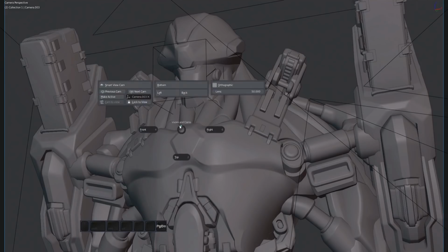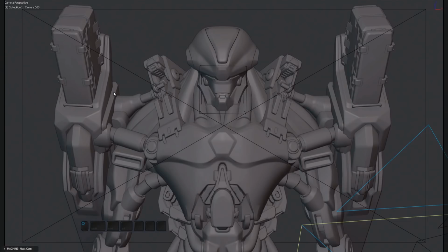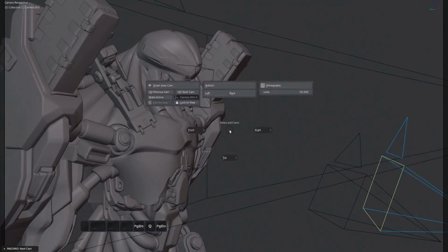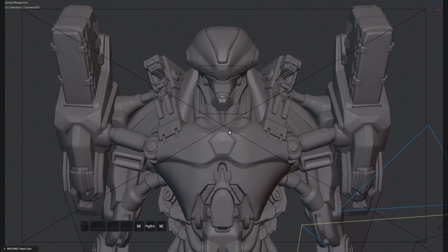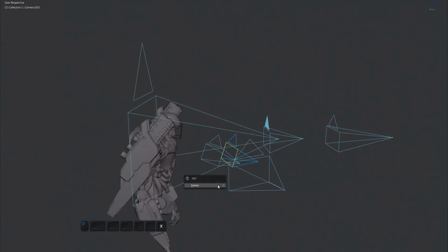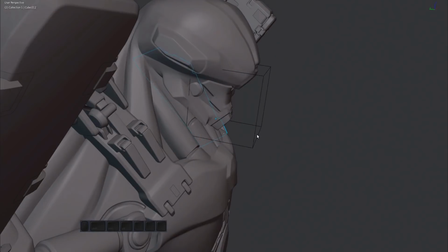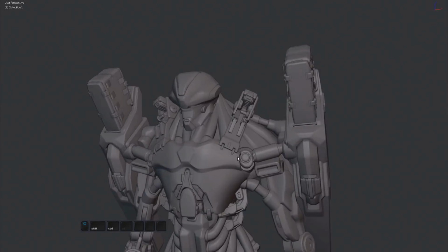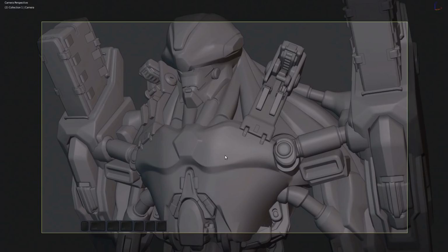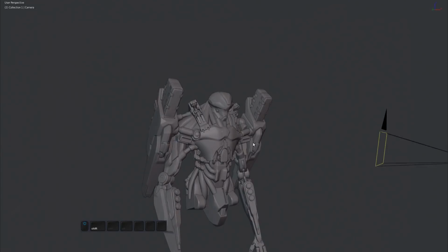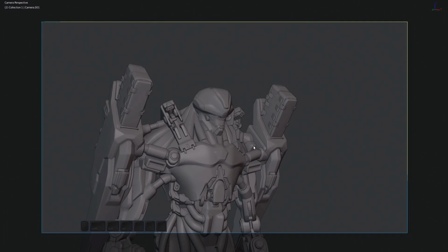You can also use the next and previous buttons to cycle through all scene cameras. Using the Q and W keys, this can be done very quickly. Without any camera in the scene, the Smart Cam will create one at the current view. To create additional cameras, hold down the Alt key while running the tool.